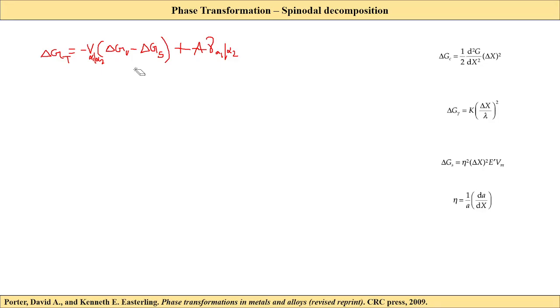Now, for delta G to be positive, the two positive terms must dominate, and for delta G to be 0, whatever the volumetric free energy that has been created from transforming one phase to another phase is being totally consumed by our volumetric strain energy to accommodate the structure, or to distort the bonds, and the second one is the surface energy, right?